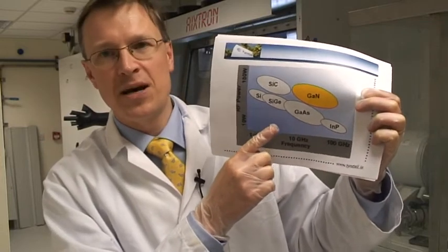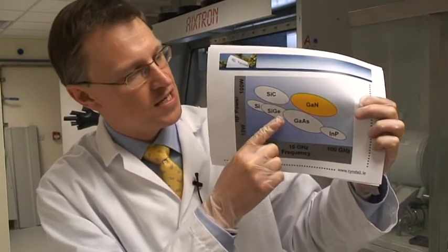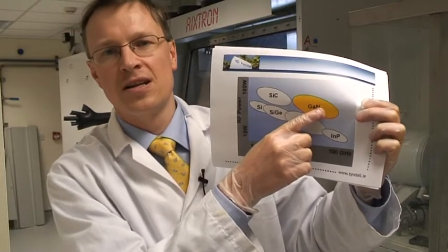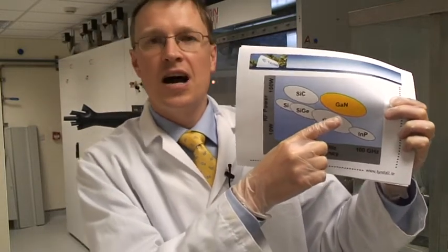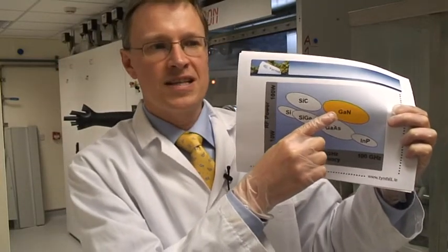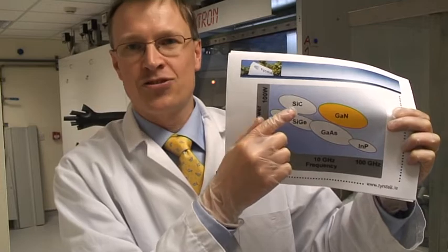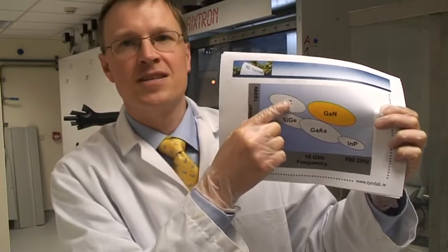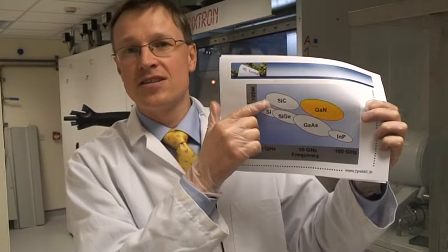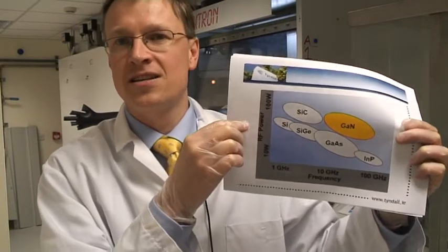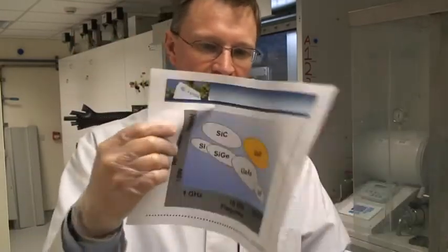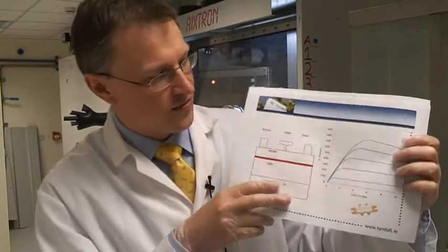However, using wider bandgap materials such as gallium nitride allow you to push up into higher power densities with higher frequencies. This has application for high frequency communication systems, and also more recently people are examining this for high power electronic devices, pushing into this space. There are advantages to operating high power transistors at higher frequencies, as this reduces the size of the capacitors you require, for example.